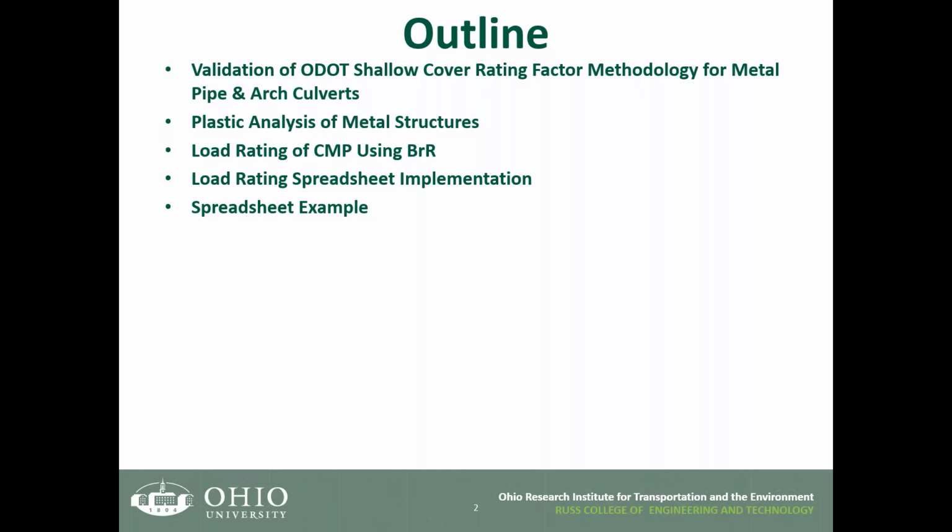Another purpose of explaining this is to give more confidence to people using the software that we have significant capacity left in our pipes, even if the bottom of the pipe is completely corroded. There is a tremendous amount of load they can still carry, because the majority of the load is carried above the spring. So the rating that Kevin will explain, the spreadsheet, is very good, but keep in mind it is very conservative.